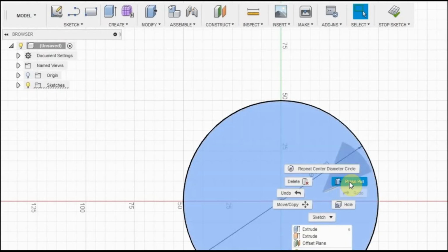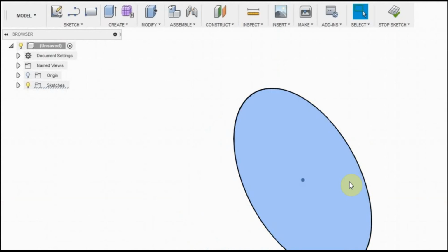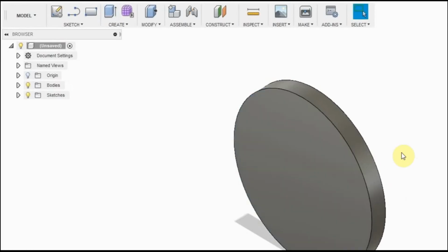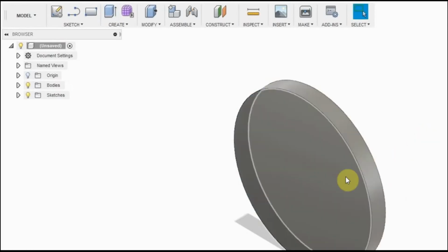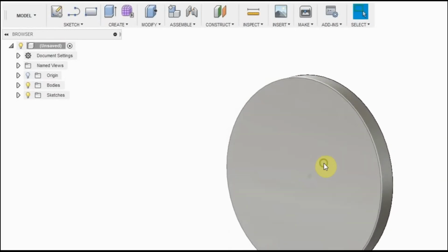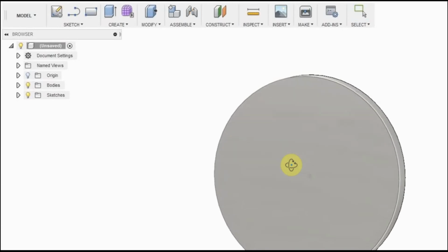I'm making that circle a 100mm circle. If you remember, I made the box a 100mm box, so this should fit. I'm giving depth to this circle of 10mm. And I actually pulled it away so it went to a negative depth. That makes it easier when you actually create the G code to go to the CNC machine.